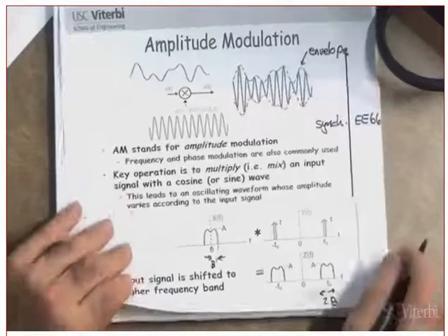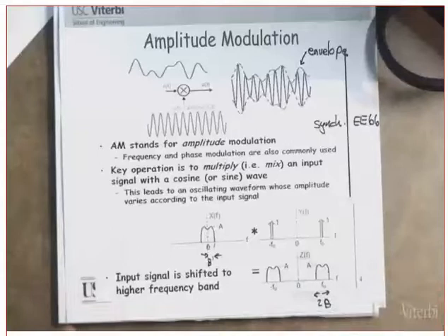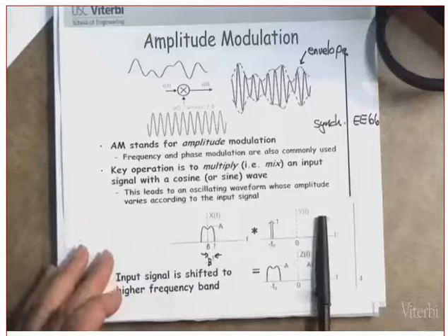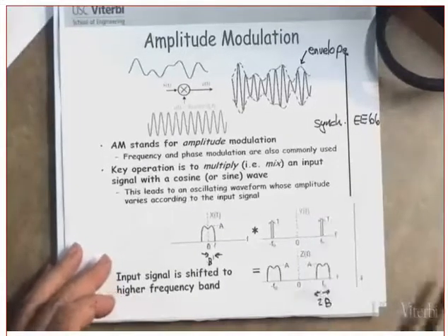Okay, good. Now, if the information is the same, can I filter one of them? What do I get? Instead of the double sideband, I get single sideband. Did you get my point or not? But at what expense? At the expense that I need to design a very sharp filter. Are you following or not?